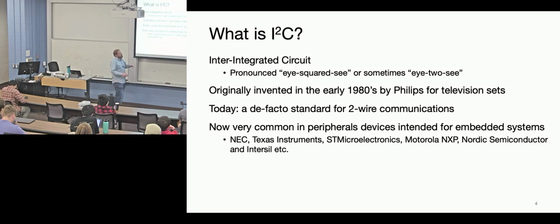In fact, because integrated circuit technology has gotten so robust, and we can get so many transistors on things for free, it's not uncommon to have a sensor or a memory module that has both I2C and SPI interfaces available. Usually there's a pin that you ground or pull up to VDD, and that tells the chip which interface to talk to, giving you more flexibility. It also helps the chip manufacturers not have to make 2 variants of their hardware, so that's a benefit from their supply line point of view.